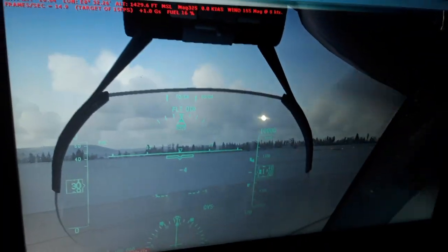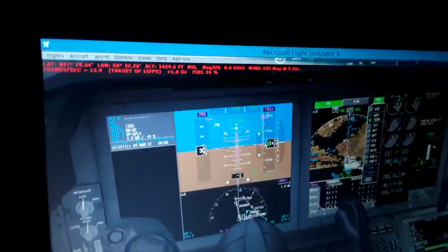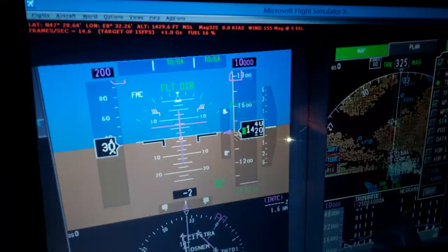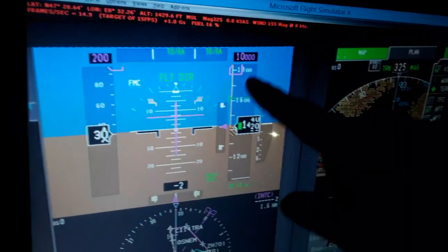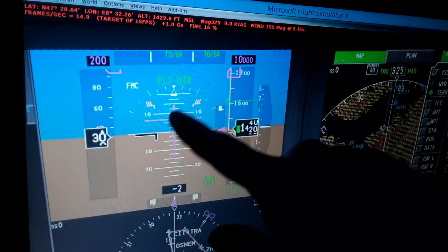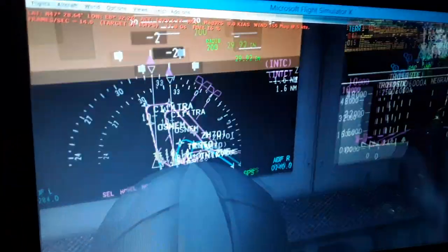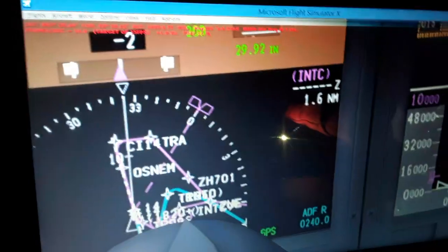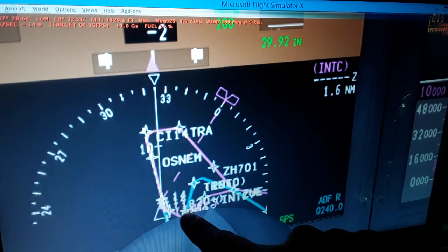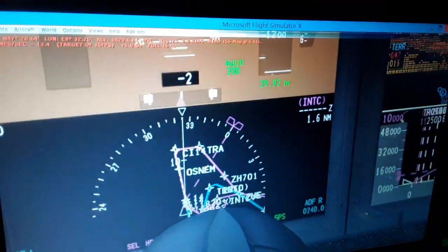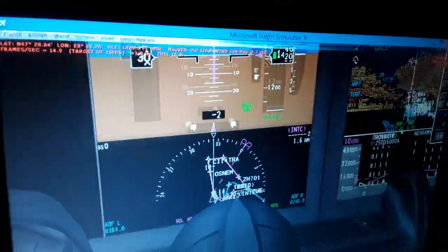It displays the same things like the primary flight display. So we have the airspeed selected and altitude selected, and the flight director across the purple. So we have also the flight plan here we created. You can see the first waypoint, the intercept to 1.6 nautical miles from the runway takeoff threshold. Then we have to climb through and then approach and land this way.